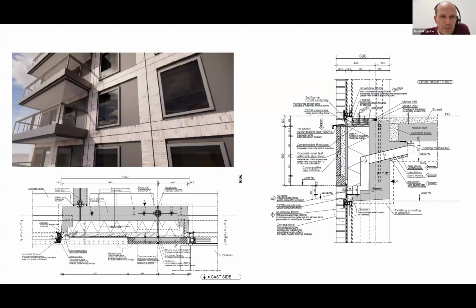That being said, we can also do brick slips, and this was one of our earlier schemes. And as you can see in this, we've got this double layer of concrete. There's the structural internal layer, and we've got this brick slips on the outside that carry it. It does create a fully filled cavity as well. So in terms of this, it's an encapsulated facade. There's no cavity. The fire risks are a lot less. We've obviously got the structure on the inside, which is very good.